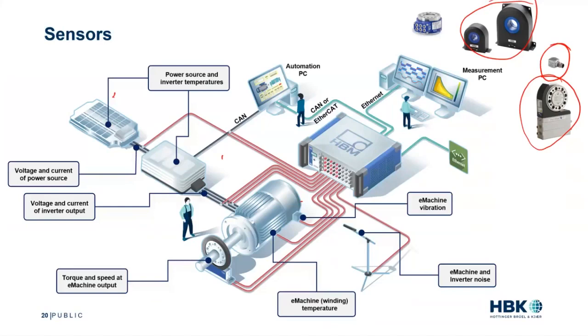So we have the ability to offer you expertise on all these sensors, and where to put them, how to mount them, how to isolate them, what the grounding structure should be. So these are all things you need to consider. In my fun little animation, we have all these sensors going back to our eDrive power analyzer. So bringing those all into a common area is something to consider. But I think with sensors, we always need to consider what's the accuracy for all of them, what's the bandwidth for all of them, what's the best way to measure them for all of them. They're these common threads.